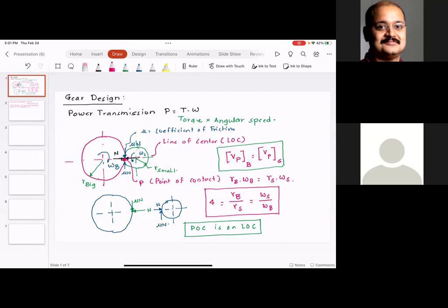So you'll come to a point where the belt drive, rather than transmitting the torque from the pedals to the wheel, would just spin and the bike will not go up. As a matter of fact, it will come down the hill. Can you visualize the situation? Because belt drives are not positive power transmission elements.